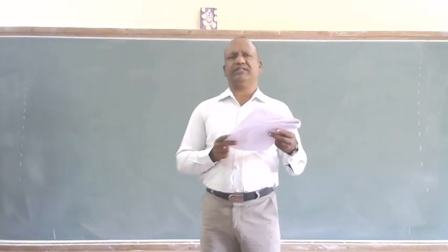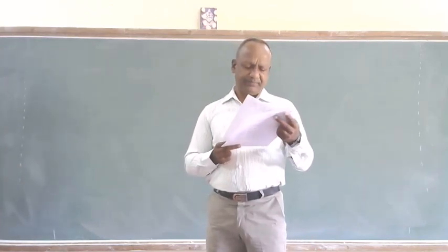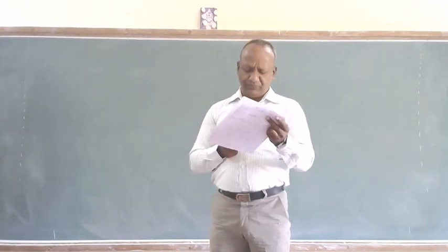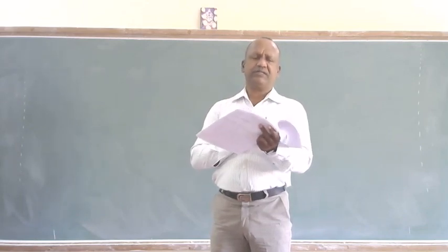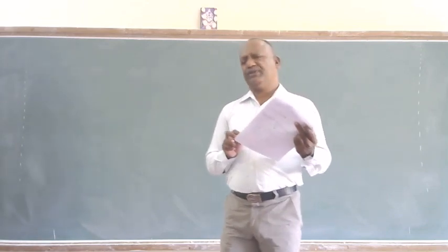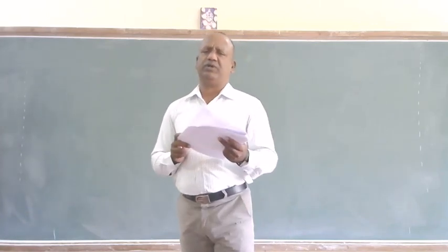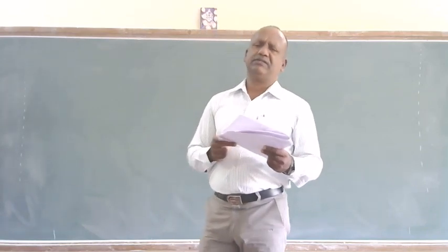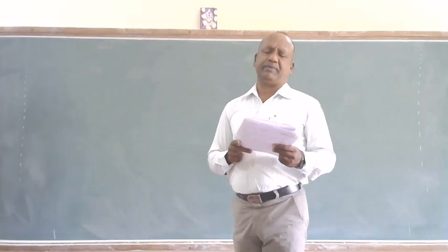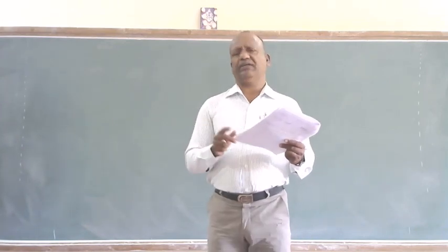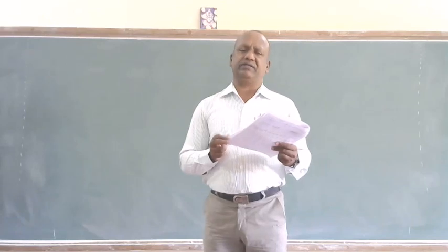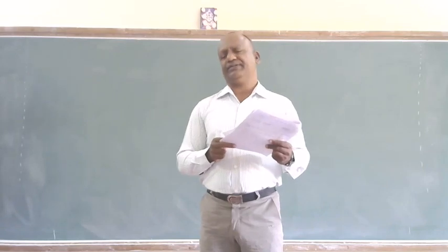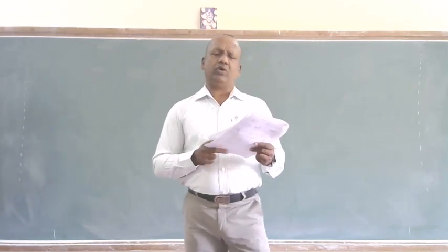So we start with the definition of a non-uniform quantizer, then when we apply non-uniform quantization, and after that the important mechanisms for its implementation, particularly compression and expansion, collectively called the compressor and expander. So generally the whole operation is called a compander: compressor, expander. The combination of these two, the compander, is always preferred in the quantization process.